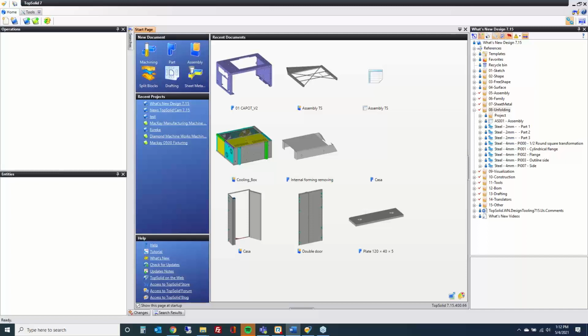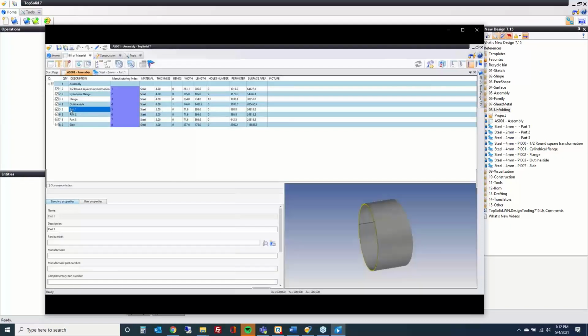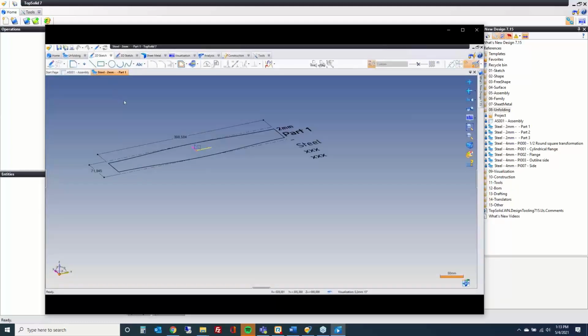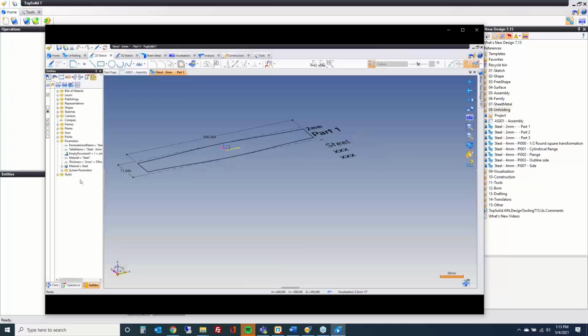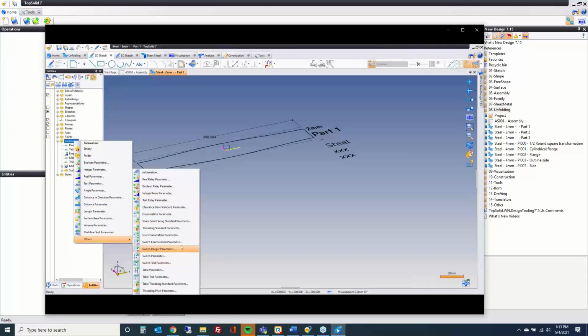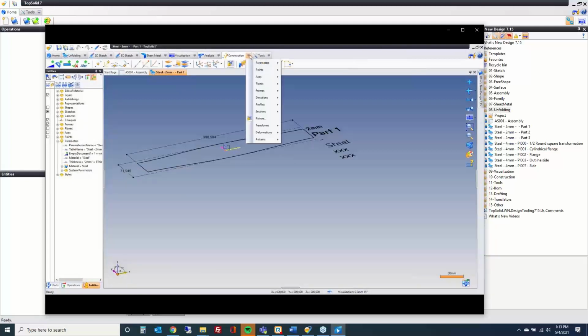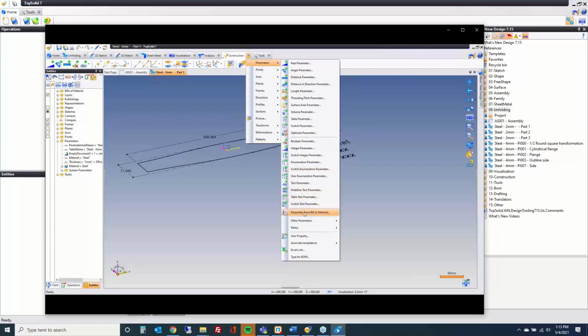All right, so in this one, basically in the unfolding process now, it is possible to create a parameter from a bill of material, okay? So for example, here I'm showing you in this bill of material, the manufacturing index number. And on this flat pattern, we're going to go ahead and create a new parameter type so that we can pass a parameter from the bill of material into this flat pattern document so that it passes along to processing properly.